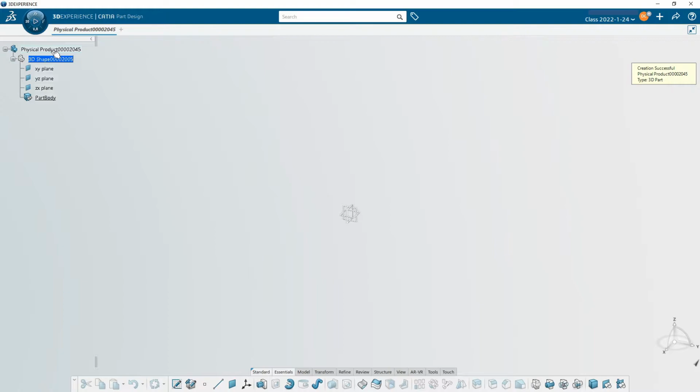But as far as the way that it works, if you go up here and hit the plus sign, it's going to make a new 3D part, but if you look down here at the bottom, we have these different icons that we can use to make things. These are all the icons from the Part Design workbench. So it seems to be, and I don't have empirical evidence on this, whatever the last one was that you used. If you used Surface Design, if you used Part Design, it will show up as that.